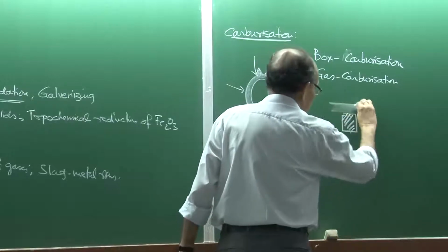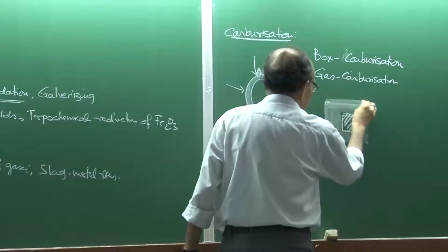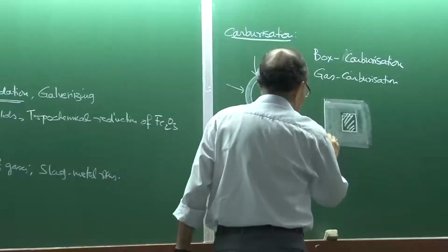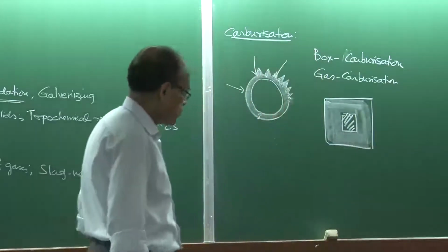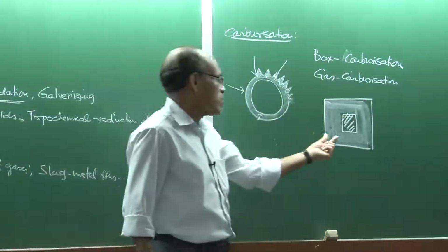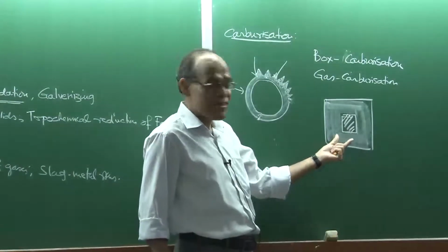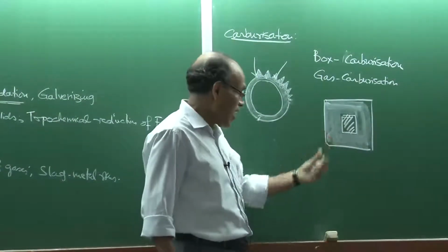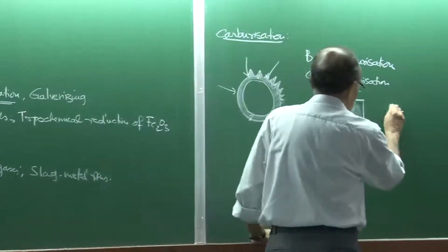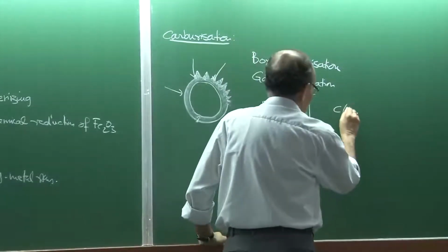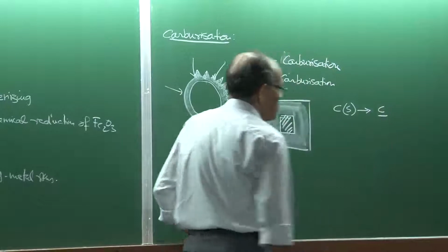and it is going to be put in a carbonaceous mixture, and then it is sealed from all sides. It is a mixture, not just pure carbon; maybe there is sometimes sodium carbonate, etc. also added, which is a carburizing agent, and as a result carbon from the solid gets into the dissolved state.